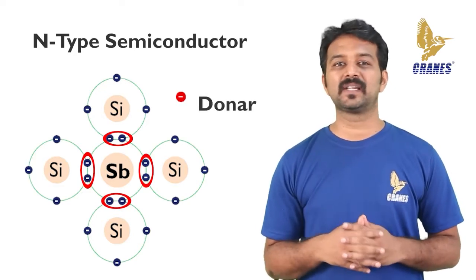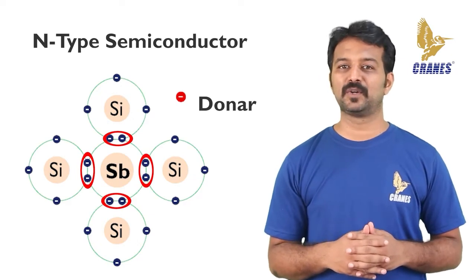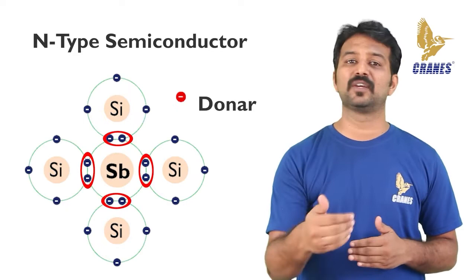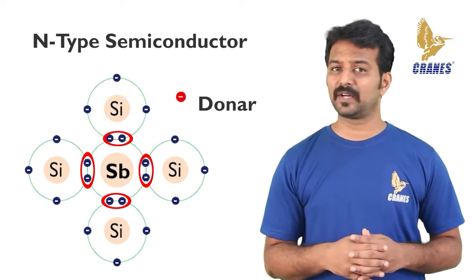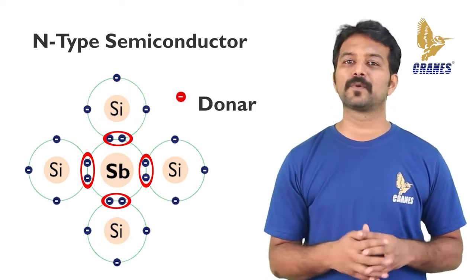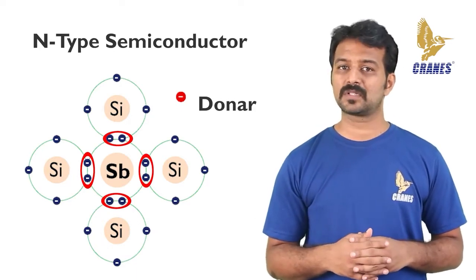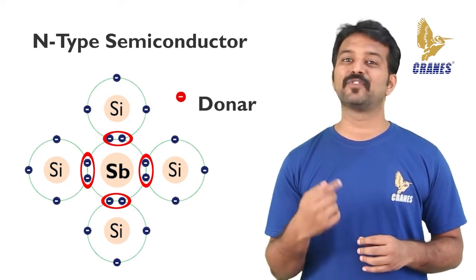The number of conduction electrons can be carefully controlled by the number of impurity atoms added to the silicon. A conduction electron created by this doping process does not leave a hole in the valence band because it is in excess of the number required to fill the valence band.